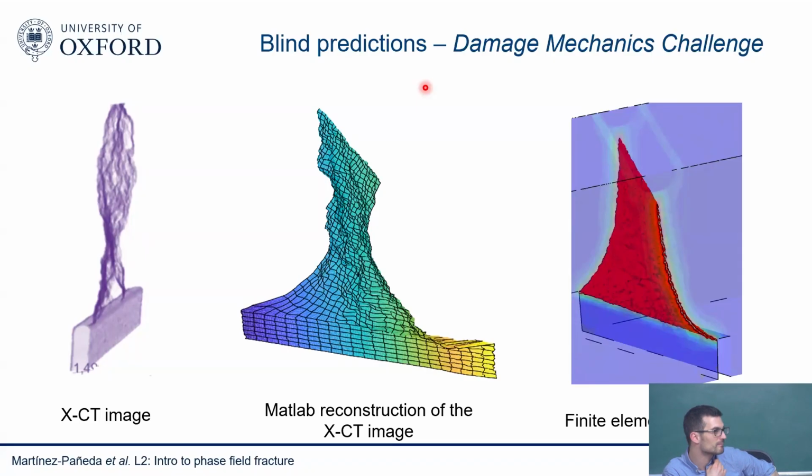So this length scale parameter, the material property, if we calculate it from the formula that you have shown, the value generally comes very high. It depends on your material. It could come high, depending on the fracture properties. So first we have to decide the mesh size or the length scale parameter, which one should we choose first? No, the length scale is a material property, so you don't have the freedom to pick that. If you have a given material and you're going to be predictive, you need to take the value that comes out of the equation. And then what you pick is your h.